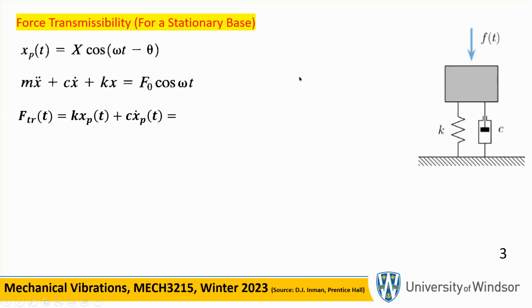We're not going to go through it, but the expression for x was given, and on the right-hand side it depended on, of course, the F naught, the static loading or the amplitude of the load, and on the stiffness and damping ratio, etc. The big thing is that x itself depends on what is called the magnification factor.